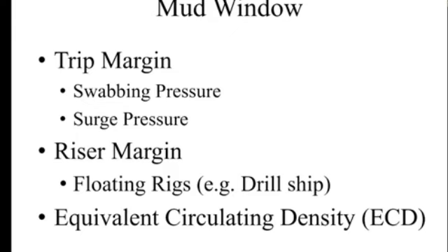Let's say the well is in static condition, meaning that the operation has not started yet, so we have the drilling mud, and the bottom hole pressure is equal to hydrostatic pressure. As soon as we turn on the pumps and we start pumping, the bottom hole pressure increases.